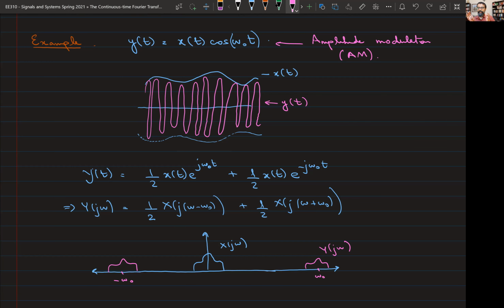To transmit high frequencies you need a smaller antenna. That's why the Wi-Fi antennas at 2.4 gigahertz inside your phone are not even visible. Otherwise, in old handsets, or AM radios, which you may remember, a long antenna would stick out. That has to be big in order to get a good reception.